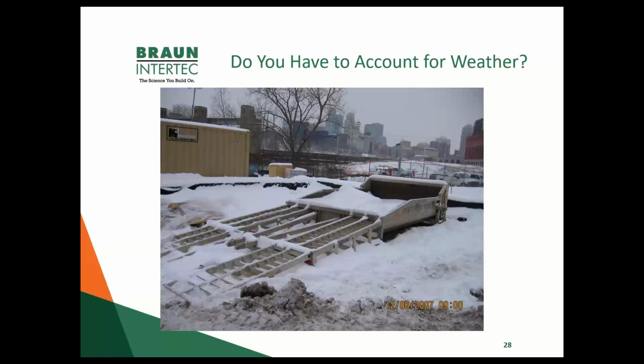That's the fun part about making the regulations meet reality: when you have containment systems that are exposed to the elements, you are required to record every time you discharge accumulated precipitation out of that containment system, both the volume and the frequency, and that the discharge does not have any sheen on it.